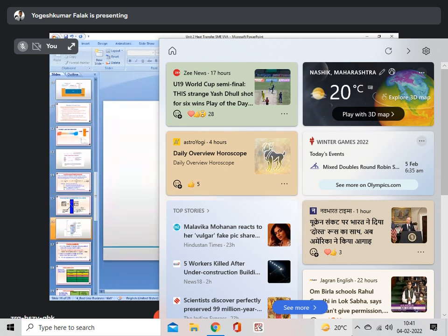Now this is one of the examples, T1, T2. That is how temperature and length are determined, and K is equal to 0.96 watt per meter Kelvin. So if you specify any material, they can give you the values directly. The temperatures T1 and T2 are used because this is Fourier's law, which concerns conduction, not convection.